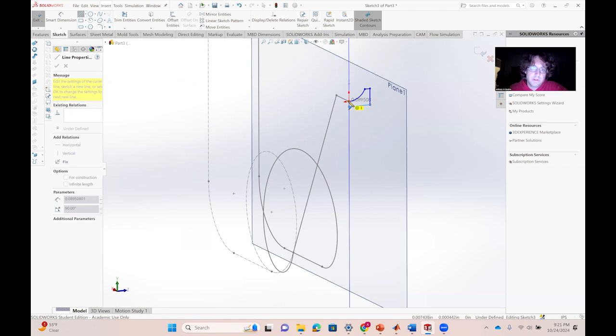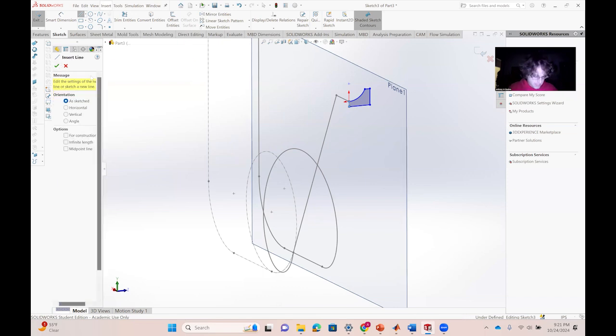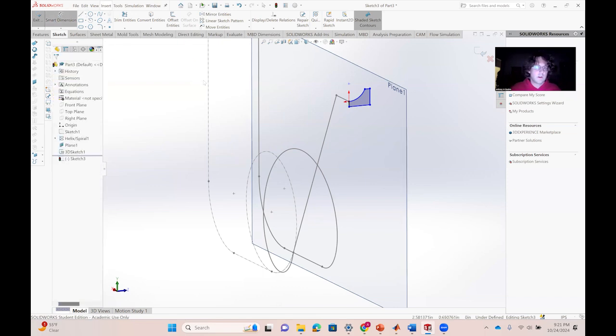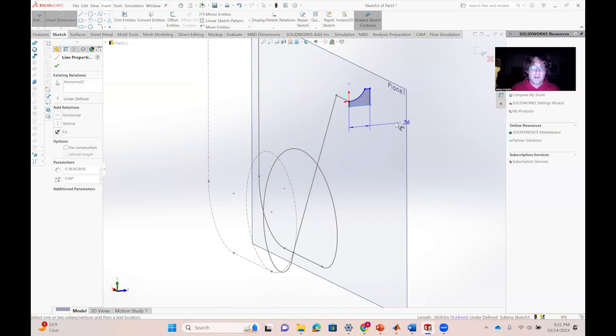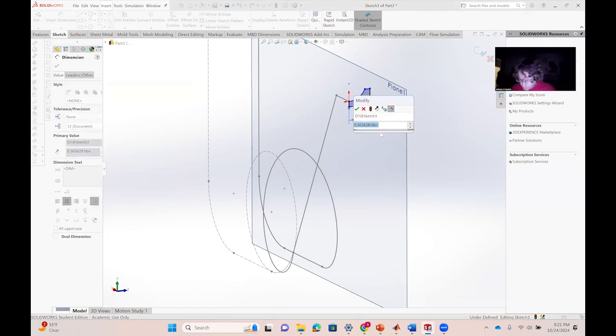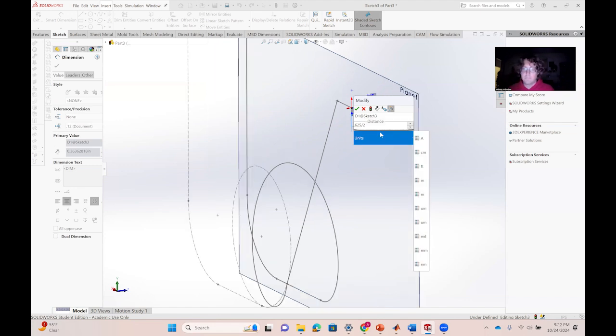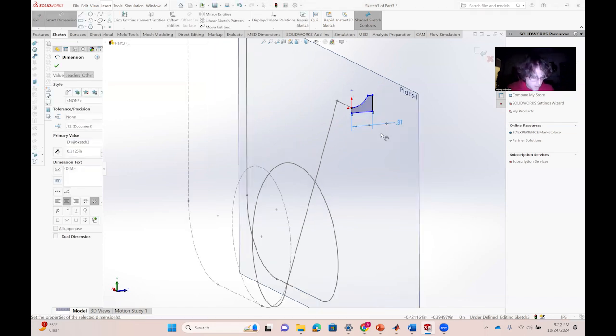And then another one directly vertical back to the origin to create a closed shape. Okay. And the dimensions I used, so I'm going to measure the width here. I want it to be 0.625 after I mirror it. So I'm going to do 0.625 divided by 2, again, because I'm going to mirror it. Okay, cool.